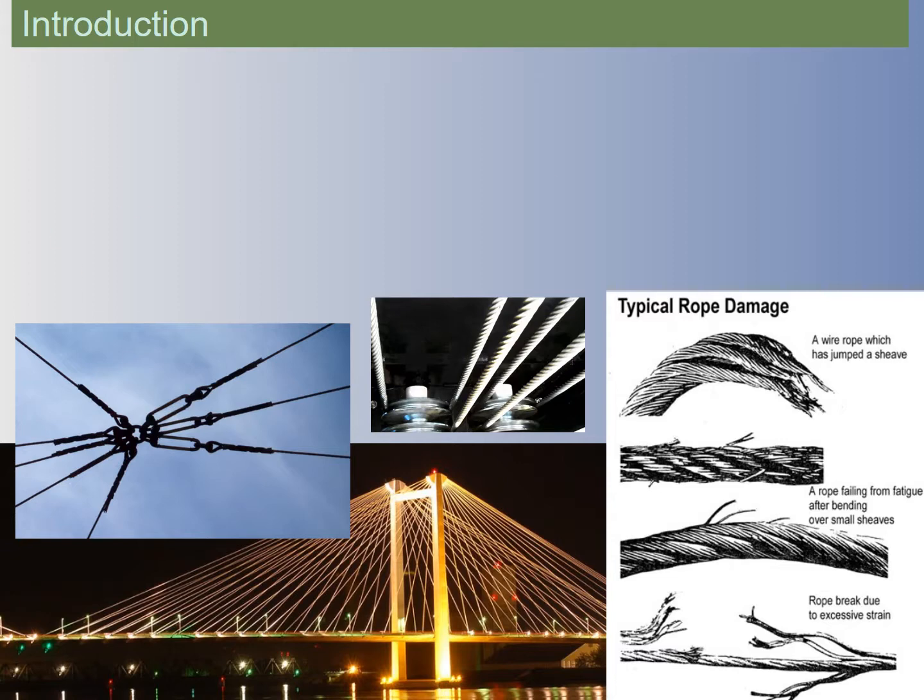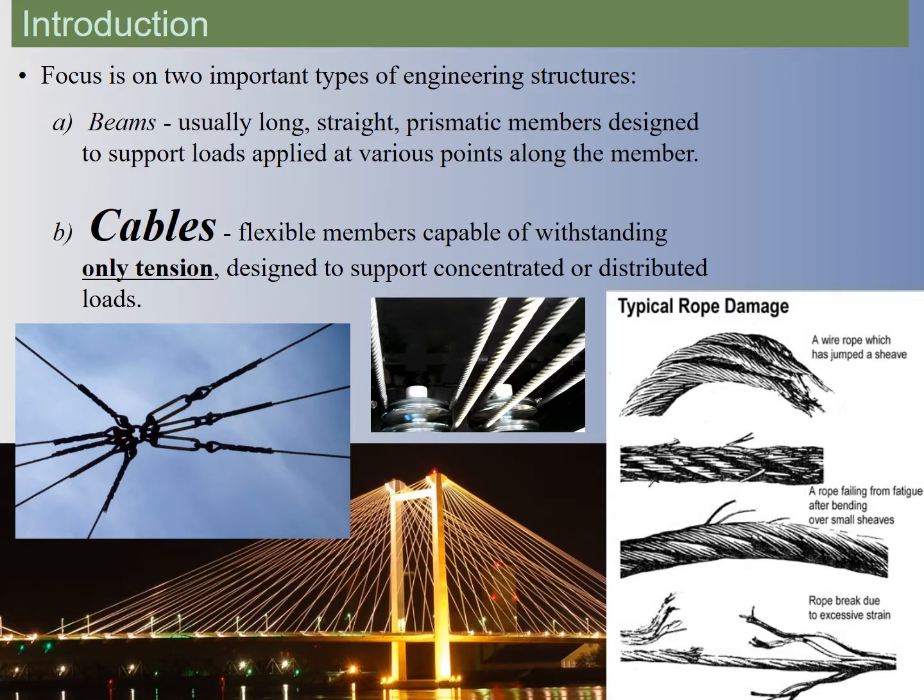For cables, the nice thing about cables is they're only in tension. And if you're ever working around cables, be very, very careful around them because there's actually quite a lot of elastic energy that can be stored in these things. So, take a rubber band and break a rubber band and feel that elastic recoil that happens when it breaks. The same thing happens with a steel cable.